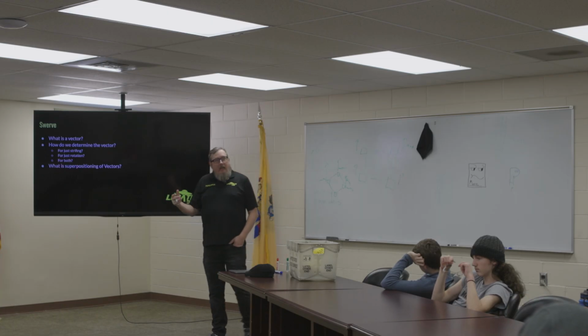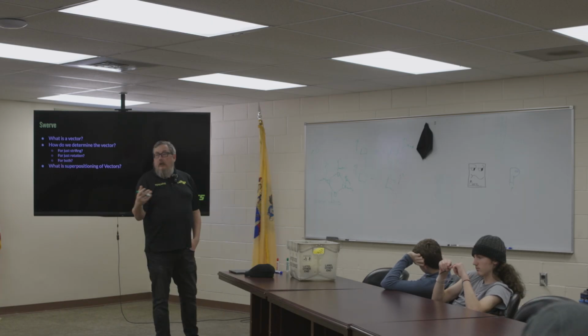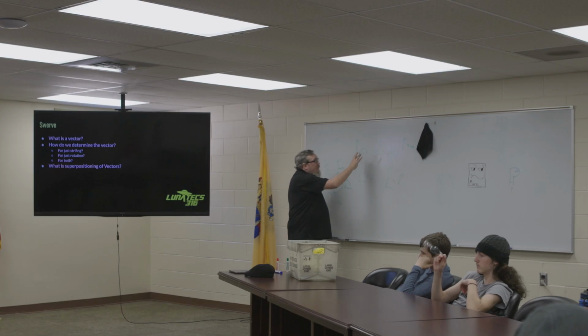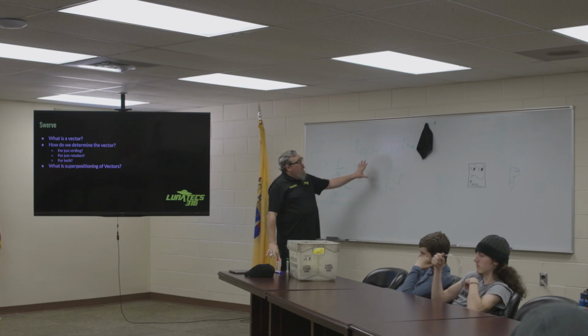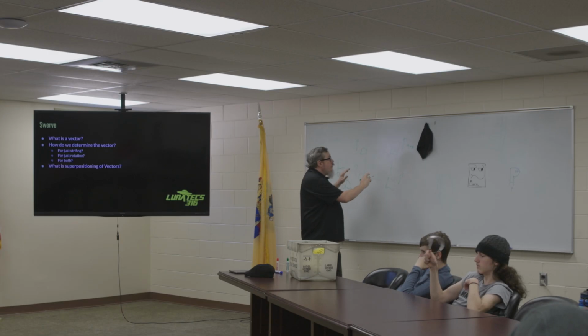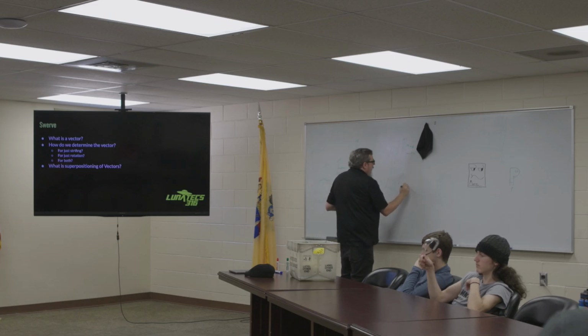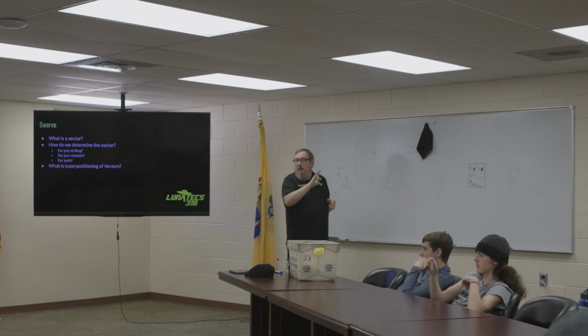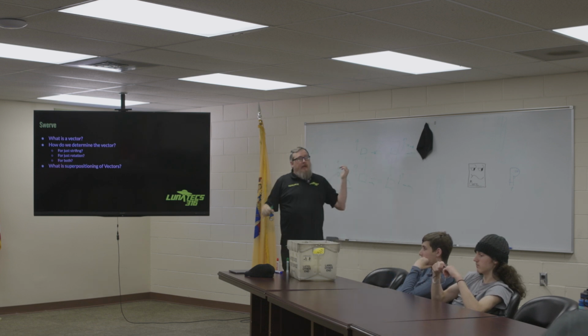If I am at 0 and I want to go 10 meters per second, what am I going to use to get up to 10 meters per second? PID loop. So I think it makes sense that I could use a PID loop to get the wheels to face this way. If I want to strafe, right, I just turn the wheels using a PID loop 90 degrees and strafe, left or right.